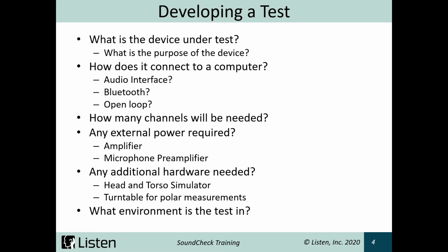How many channels are needed? For just a single device, we need at minimum one channel for an input. But if I wanted to take multiple tests of the same device, maybe I want the frequency response and impedance of a loudspeaker, I would need two inputs. Or if I had a microphone array, however many inputs I have in that mic array, I would need that many physical inputs.